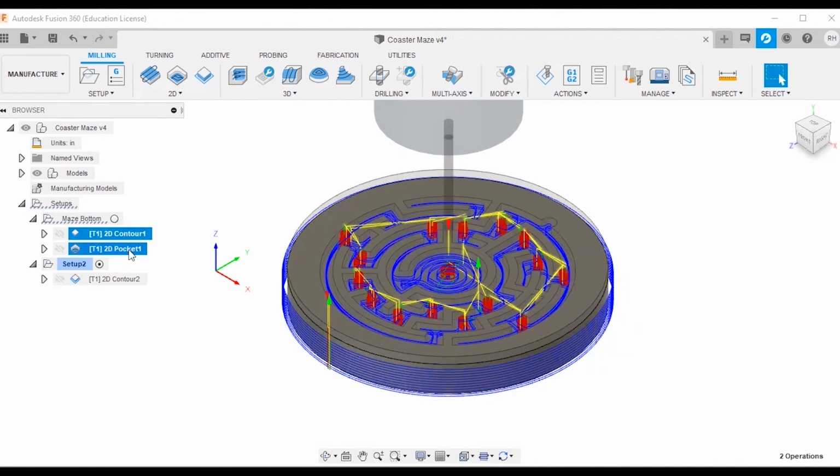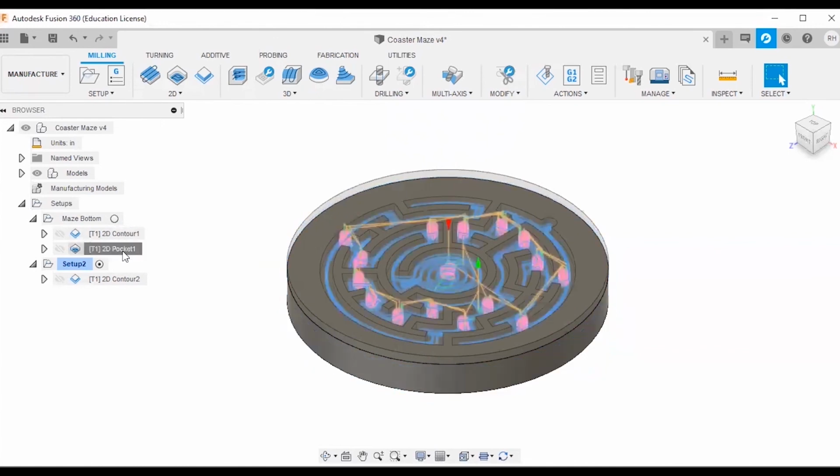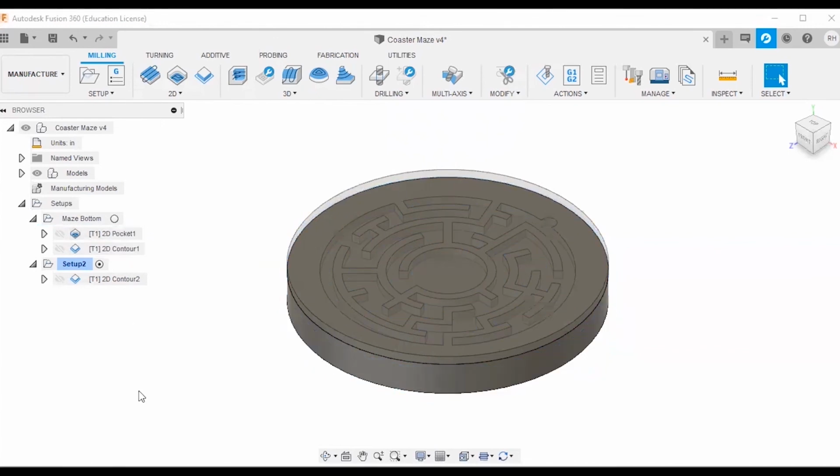And that's probably not very ideal because we lose the ability to hold the part if we do the contour first. We might lose the part on the CNC as it's running if we're running this pocket secondary. So if you had created the paths out of order, you can rearrange them by just dragging and dropping. So now we will go to the machine and cut the part. And this is a good point to save.